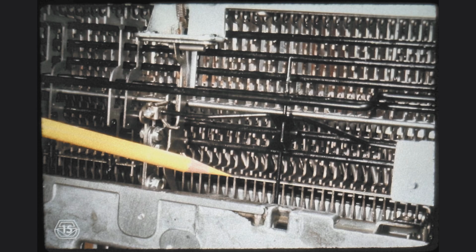Examine also the plugs at the ends of the compensator tube, holding the steel balls inside the tube. Besides holding the steel balls inside the compensator tube, these plugs are also responsible for the rather fine adjustment of the clearance between the steel spheres inside the tube.